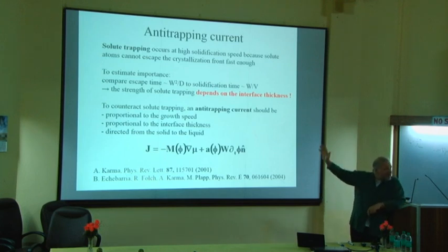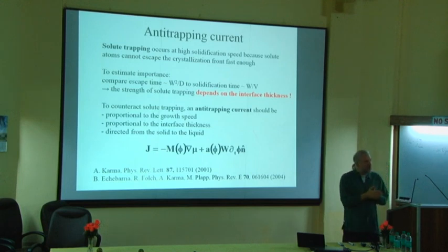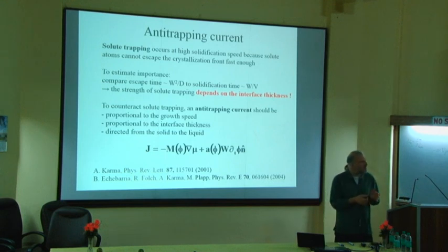Here I'm treating the isothermal situation, but just think of a normal metallurgical process. Usually solidification occurs by the extraction of heat. But the extraction of heat can be very quick because heat diffusion is fast, whereas chemical diffusion is slow. So you can have that the speed of a crystallization front is set by the extraction of heat.